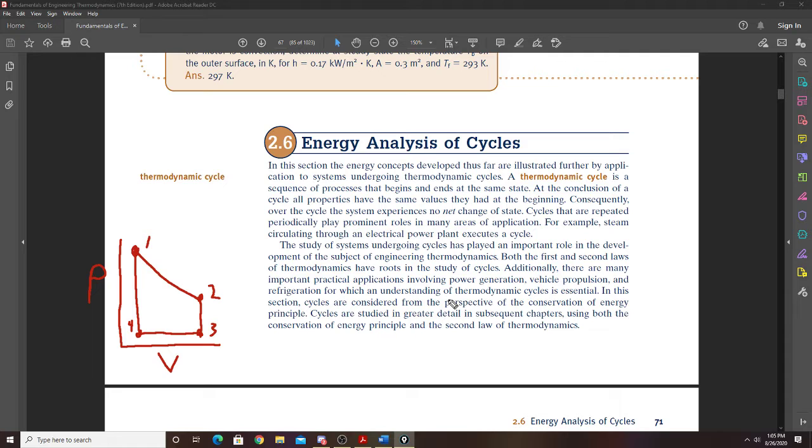Then it's the compression phase where the piston pushes all the way to the top. Then the spark plug explodes the gas-air mixture and sends the piston back down. And when the piston reaches all the way back down, the exhaust goes out, and then air comes in using valves. So whenever the piston gets all the way down to the bottom, it is at the exact same point as it started.